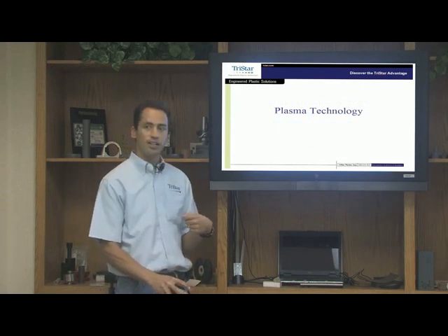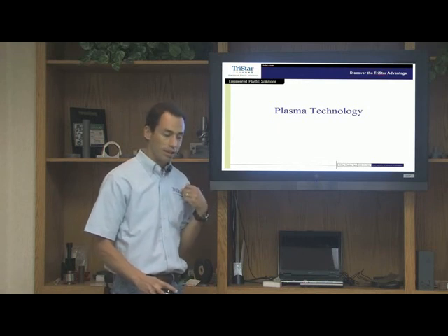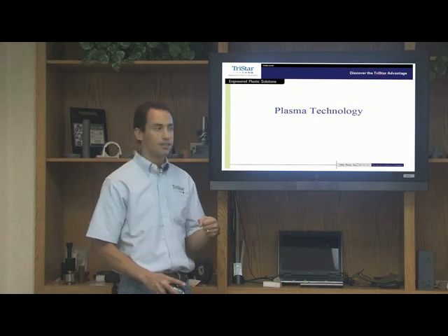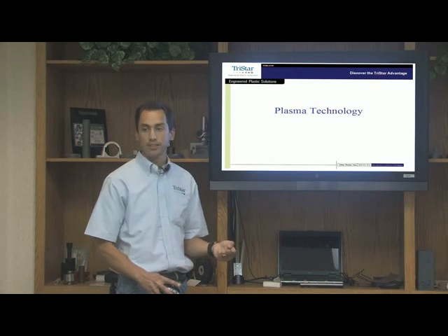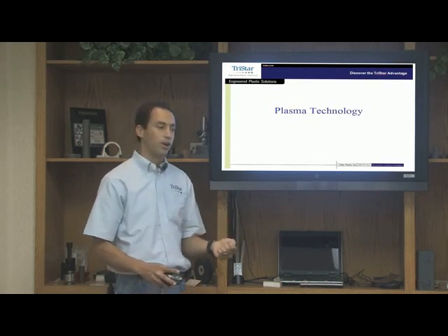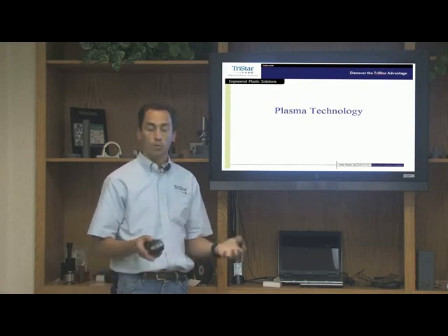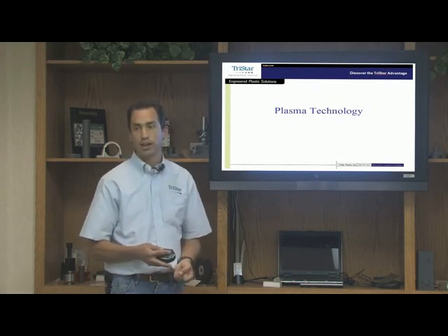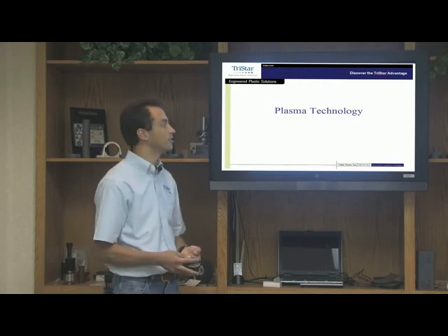So just to recap the adhesion theory, what we want to do is exploit hydrogen bonding and covalent bonding as much as we can. And that is done with surface activation using plasma organosilanes. And when we exploit that adhesion theory, we also have side effects of surface roughening, and with all those working together in conjunction, we get extraordinary bonding strength, and we can advance materials in laminates.